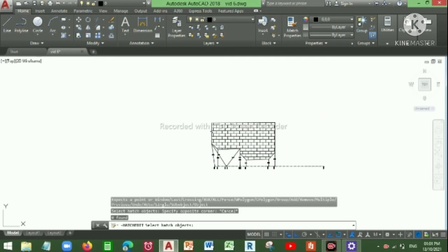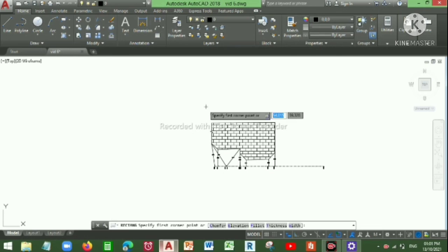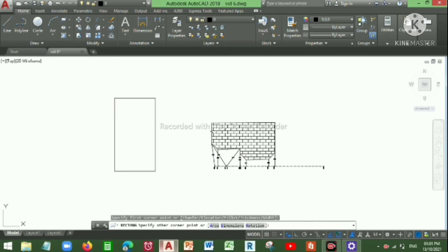The size of A3 is around 41 into 30, a bit bigger than that, so you can click on Ctrl P and get a preview of your CAD drawing. And what you can do is draw the box of dimension 40 into 25.5, and by doing so, your drawing will look much more presentable. Click on rectangle, click over here and put on a dimension of 40, tab, 25.5 centimeters.